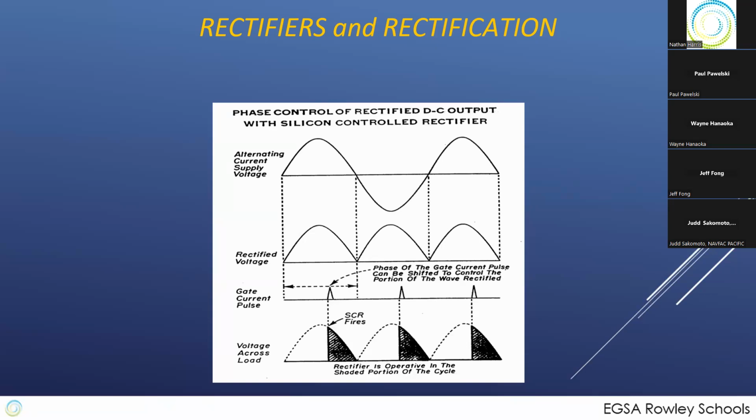And the problem with this is, if there is a grounding issue, if there's corrosion between the grill over the air exhaust and the rest of the metal building frame, if there is a grounding jumper that came loose, you don't have a full cage anymore. And that means then that EM pulse can get in and fry stuff.